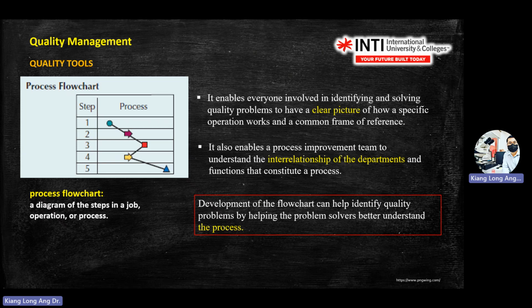We talked to you about process. Again, we are now in quality management, meaning how you measure quality. You will measure quality at the final product. Let's say you already manufacture one product at the end of the production flow, and you find out that this product actually has some defect. Then you need to check back at which process had the problem. With the process flow chart, you can pull out the first tool to see which process actually happened.